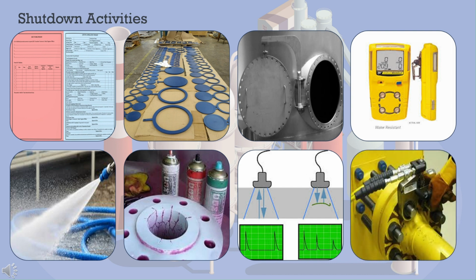Box up trays and manways carefully, usually from bottom to top. Remove temporary lighting and air movers from the equipment before final box up. Deblind and reinstall connections, torquing bolts in the correct sequence to ensure leak-proof integrity.